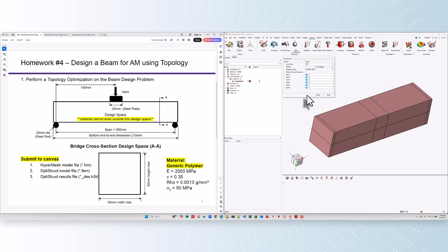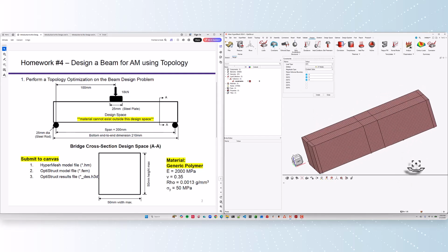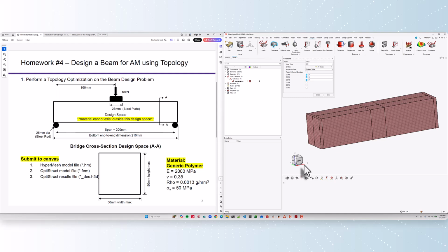And now what degrees of freedom do I set on that line? Clearly for solids, you can't apply rotation, so DOF 4, 5, 6, which is rotation XYZ, are gone. I know I need to fix Z, right? This is sitting this way, and so I know Z is supported, so Z has to be fixed. And I don't need a Y right now. Well, I know that I need to take out rigid body rotation. Z has nothing to do with rigid body. That's being resisted by the roller. But I need to take out rigid body rotation, so I will fix this whole line in X. Because on this side, I'll only fix Z. I won't fix X so that it can move freely in X. So it's just an easy way to do rigid body.